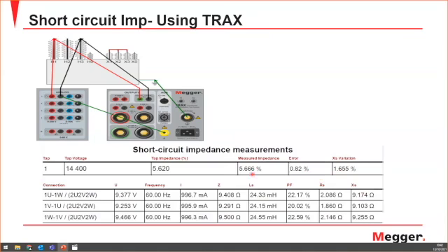This measured impedance is going to be the same always, unless you start having more shorted turns within your transformer, which can even be proven by the ratio test, but this is another way of seeing it. Also, as I said, deformation of the winding is a good thing to detect, whether you have it or not.